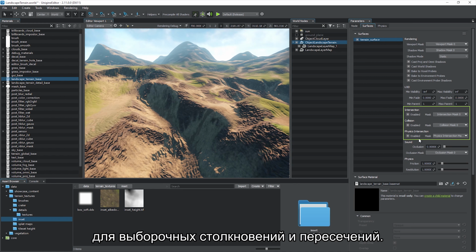Intersections are detected with a variable precision, starting from a lower value and ending up with a higher one. Normally, there is no need to change these values. However, in case of detection errors, you can tweak the precision parameters, as well as enable bicubic filtering of textures for optimum balance. Be careful, as it may significantly affect performance and accuracy. Also, make note that details don't participate in collision and intersection detection, so it is not recommended to apply intense displacement using details, since visual inconsistency may appear.